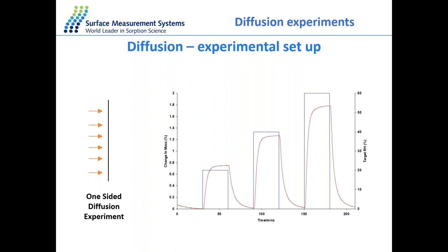Here is an example on film material. This is an experiment on diffusion, and what we are measuring here is the diffusion capacity of the sample. We have a polymer membrane, which can be used as an insulation. In this case, we have isolated one side of the membrane. We want to measure the diffusion coefficient of this material at a specific temperature, in the presence of water.